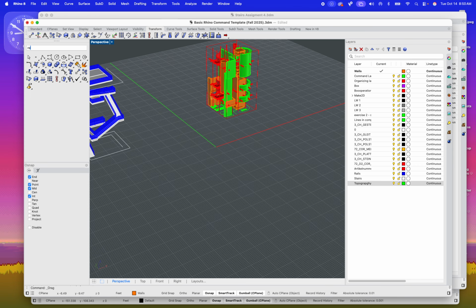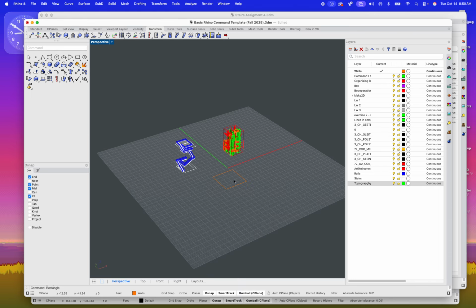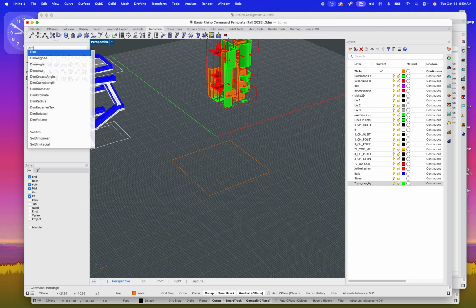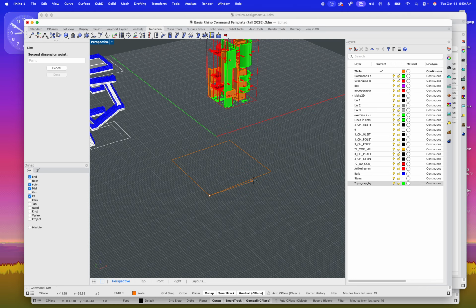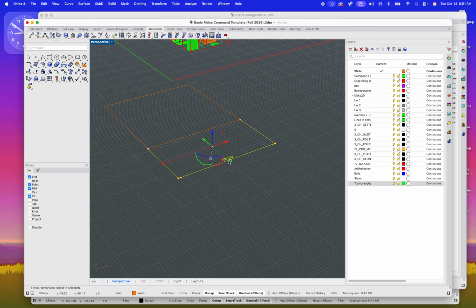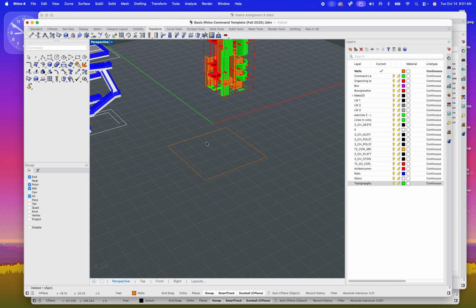Let's go ahead and make a 48 by 48 rectangle, because why not? 48 feet by 48 feet. Some of you guys were actually realizing that you had gigantic scales and different units, but there was nothing to fear. We could scale the entire thing at a certain distance at any given time. However, it's always good to make sure and do DIM and check your dimensions, right? Of course, 48 units is definitely 48 feet, so we are in the clear.